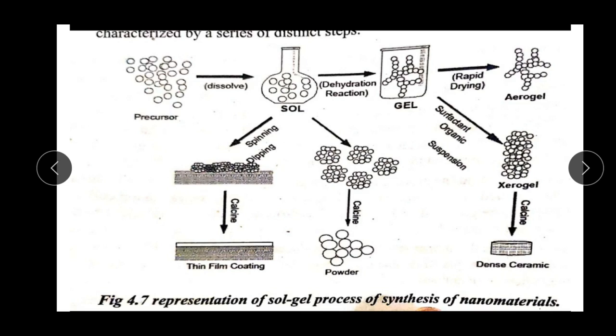The third step is the aging of the gel. During the polycondensation reaction, the process continues until the gel is transformed into a solid mass, accompanied by the contraction of the gel network and the expulsion of the solvent from the gel. The aging process of the gel can exceed 7 days, and it is critical to the prevention of cracks in the gels that have been cast.